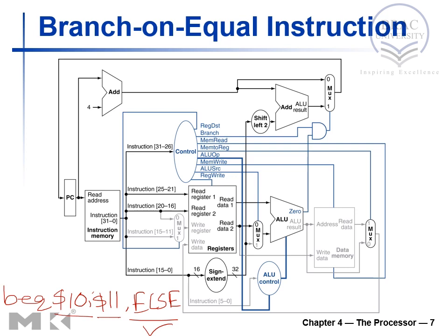This is a 16-bit value. We all know that because branch is an I-type instruction. Since this is going to generate a memory address, this needs to be converted into 32-bit, obviously sign extended, and left shifted by 2 just to make it word aligned.